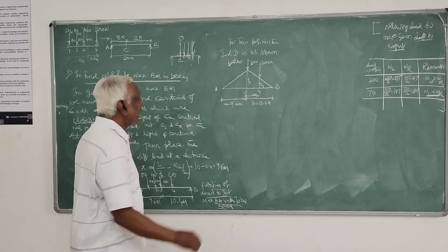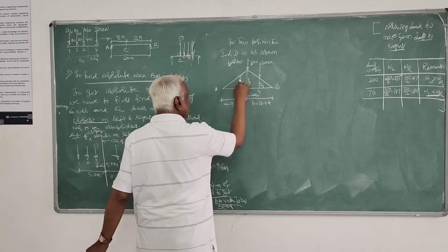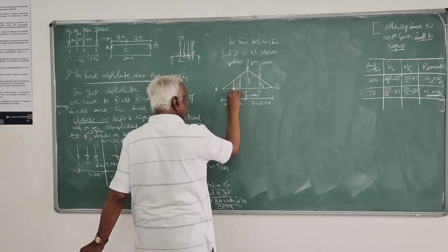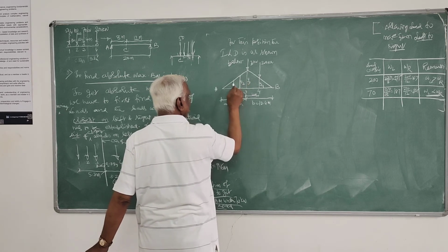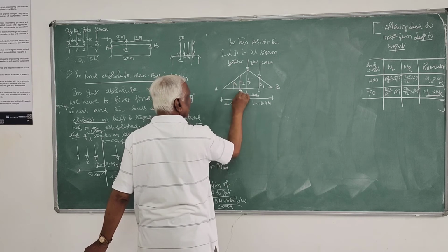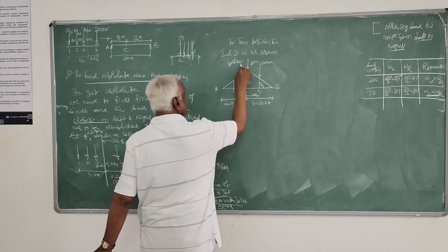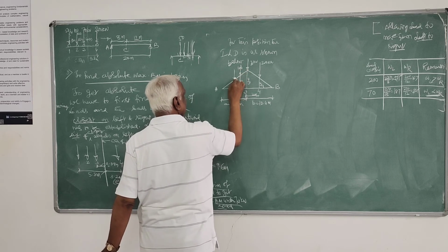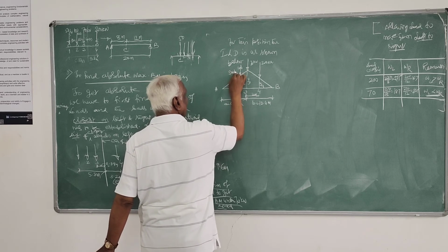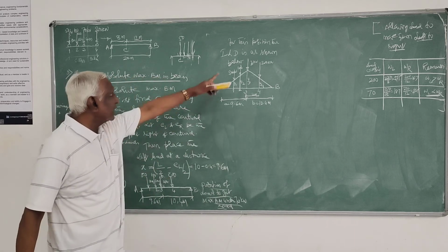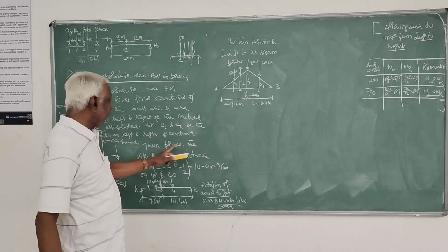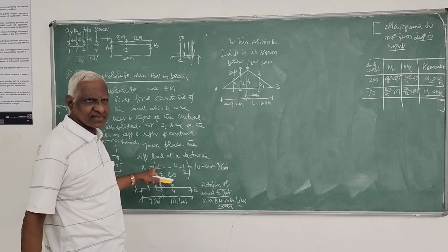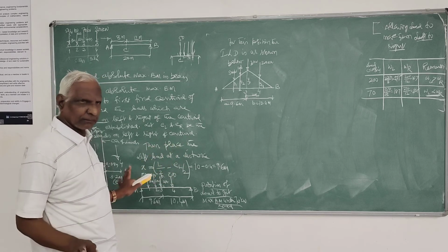And the other two loads will be here, the ordinates. So this is y2, this is y1, and this is the 100 kilonewton load, this is the 50 kilonewton load. Where that load is, you have to find out this distance from that. That's all you have to remember.